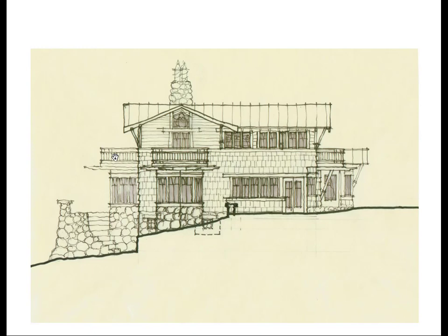These are detail items. You don't want things like hatching, which we talked about last class, to have really thick line weights, because then it would be really abrupt and loud when you plot it to your floor plan. Whereas if you look at this elevation here, you can see that the shingles and the little detail items are much thinner and a lot more faint.